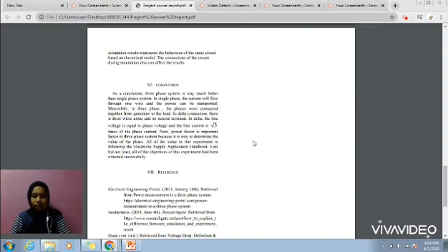And next, the power in single phase also keeps pulsating, and even when the voltage and current are in phase, the power is zero twice in each cycle. However, in the three-phase system, the power delivered is almost constant when the loads are in balanced condition, as we can see in our YY circuit just now.